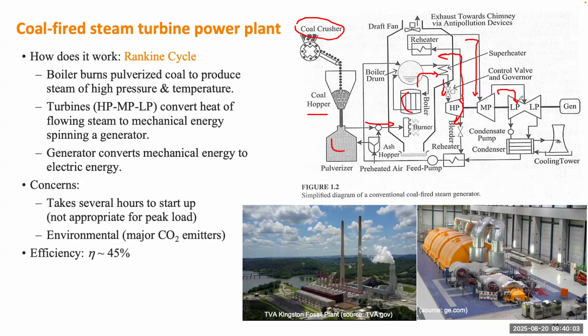To calculate efficiency, we can utilize the Carnot cycle formula to give an estimate. Let's assume the temperature inside the boiler or the burner is as high as 550 degrees C. The steam leaving the turbine, through the cooling tower, will decrease to around ambient temperature. Let's just put 20 degrees C. And let's assume other efficiency not related to the thermal part is 70%.